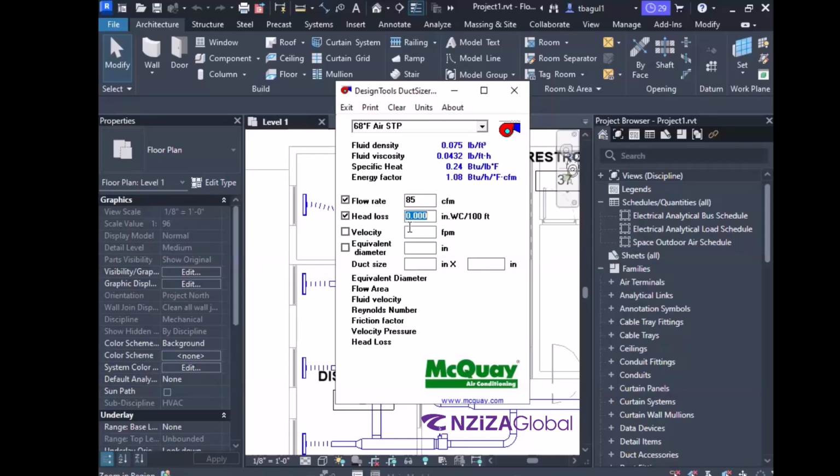Okay, what will this be used for? This will be used for calculating the external static pressure that we were talking about the other day. What is that? You have an air handler, correct? You have fans in the air handler. The fans are supposed to push the air to the last possible point.